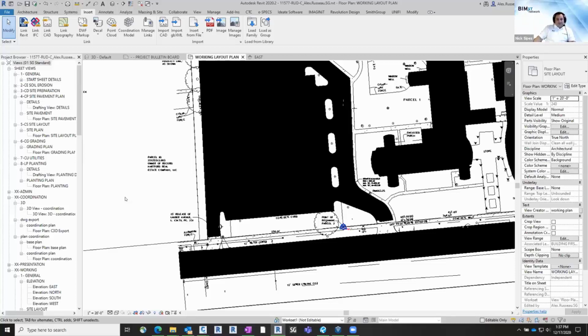So, yeah, there's multiple ways to get to this end solution. The key is just doing it early on in your project. You want to make sure you get that set up early. It just makes life a lot easier. Exports coming down from Revit for civil engineers, we can just bring it in on 0,0,0. Same thing. You can bring in the updated layout file into Revit later, and it's going to drop in where we want it to. So setting it up early is the biggest key.